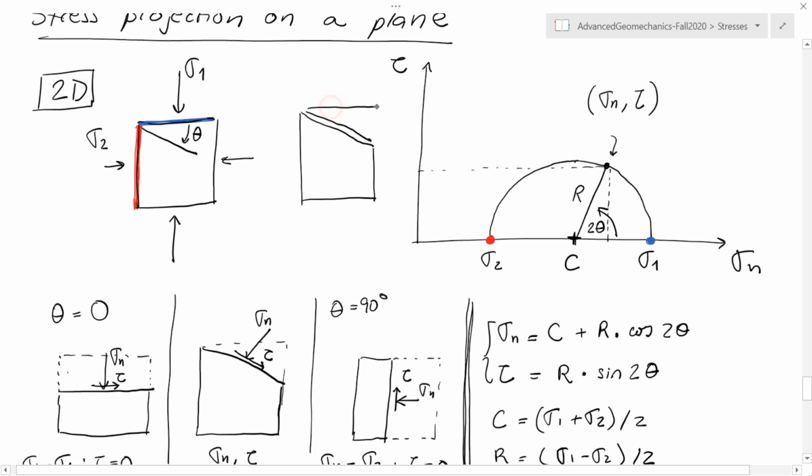Whether these 2 parts move with respect to each other under the same state of stress that we are considering, whether it moves or not, is going to depend on the ratio of shear stress over effective normal stress, and whether this one is equal or larger than the friction coefficient. We're going to see this later on, but this is something pretty important.